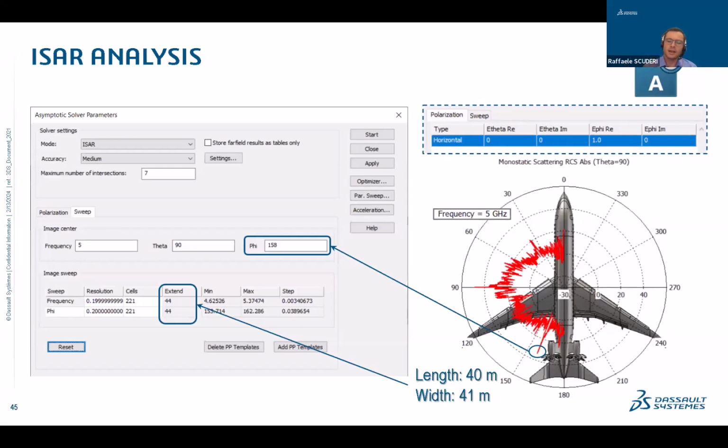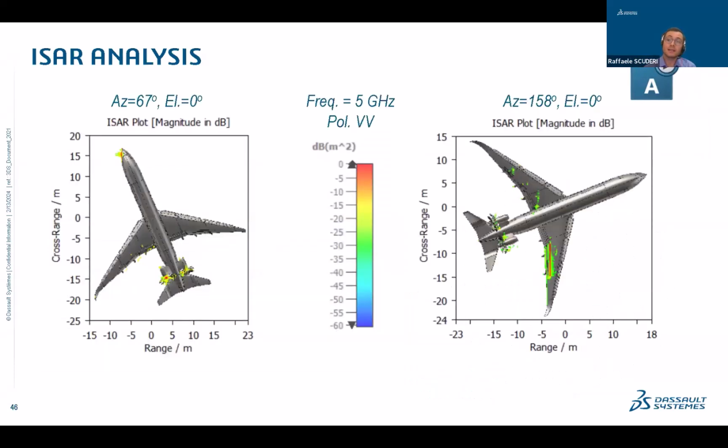So I start learning about what's going on with my target, and I run my range profile, I run my hotspot, I can check rays, I can run the inverse synthetic aperture analysis here. And the result, as the name of the analysis already says, is an image. Okay, and it's really a picture of my model.